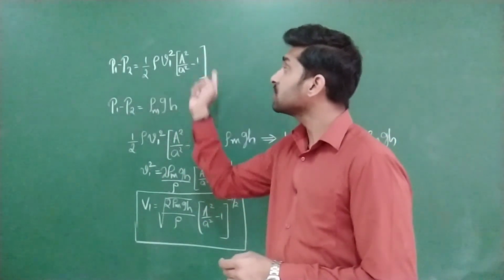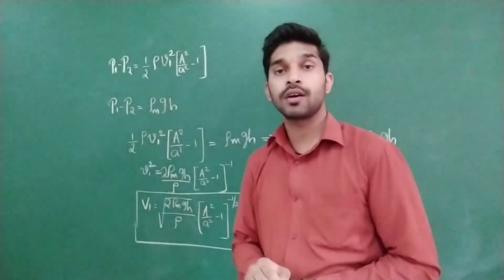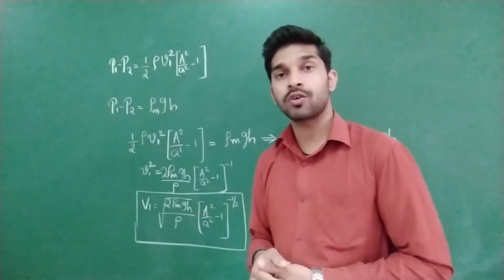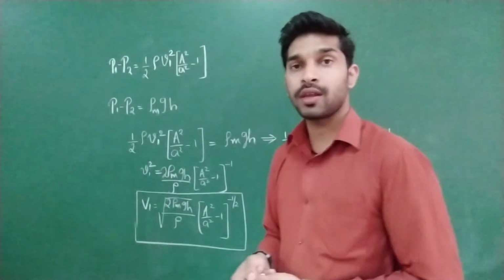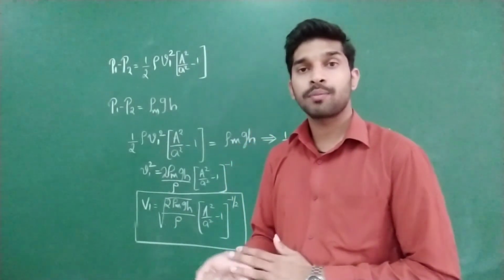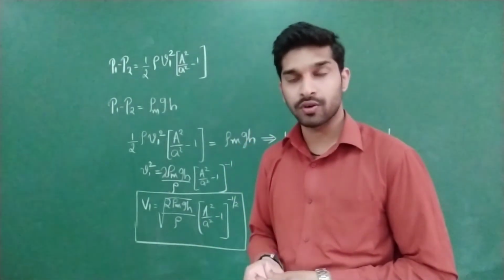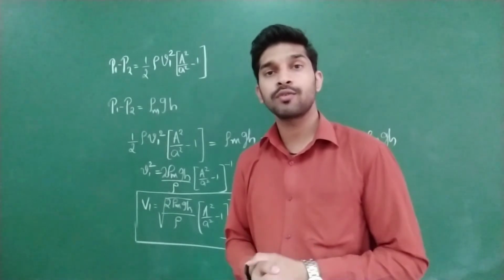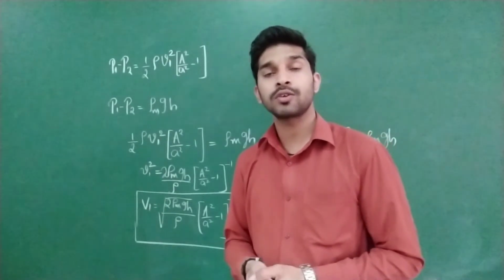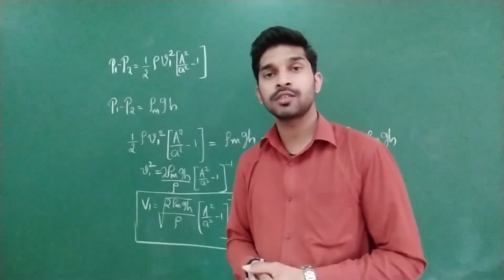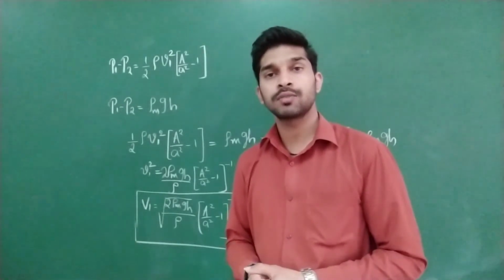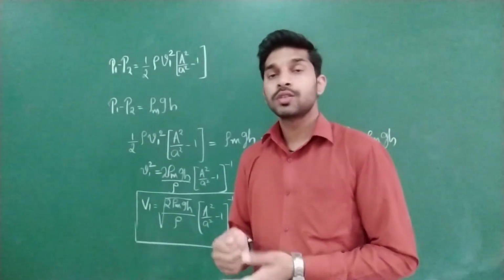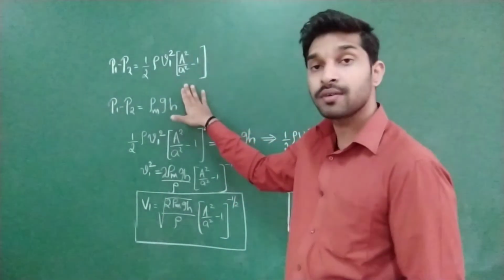Okay. Next, due to this pressure difference, what will happen in that U-shaped tube? Okay, due to this pressure difference, that liquid will rise again on the constriction side. It will just rise again. Why it will rise means at constriction what will happen? Cross sectional area is completely minimum first of all. So if cross sectional area minimum means what will happen for the pressure? Pressure value will be minimum, correct no? If velocity is maximum over there, if velocity is maximum means what happens for pressure according to yesterday's Bernoulli's equation? It is nothing but what? Inversely related. Okay, so that's why the liquid will shift.